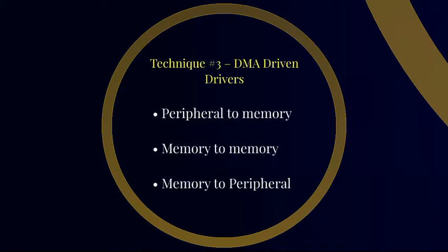Technique 3: DMA driven drivers. There are some drivers that move a large amount of data through the system, such as I2S and SDIO. The idea behind these drivers is that the DMA controller can move data around the microcontroller in the following ways: peripheral to memory, memory to memory, and memory to peripheral.